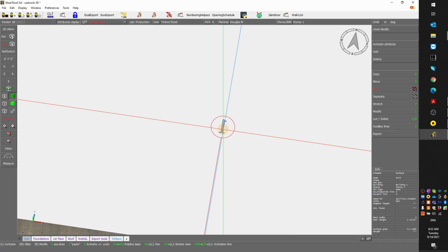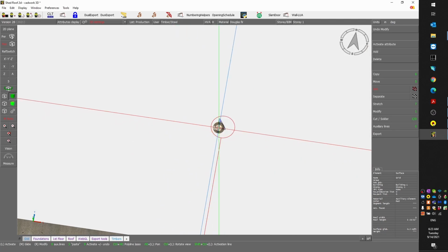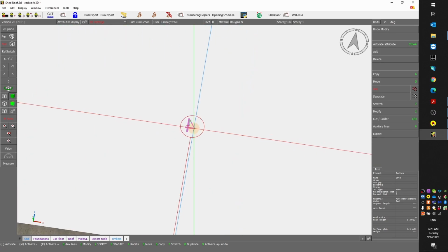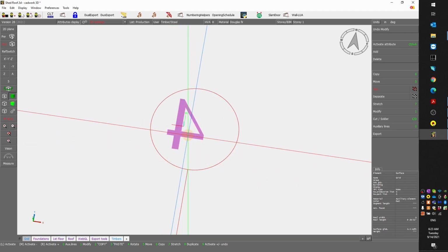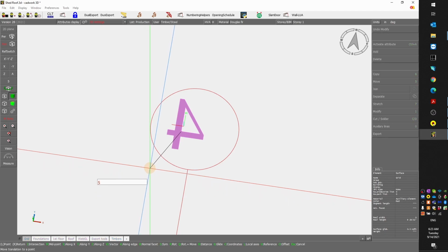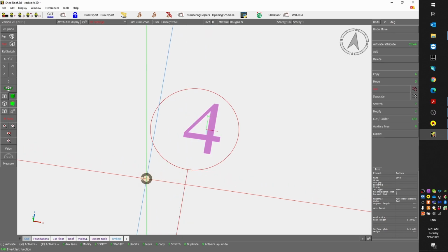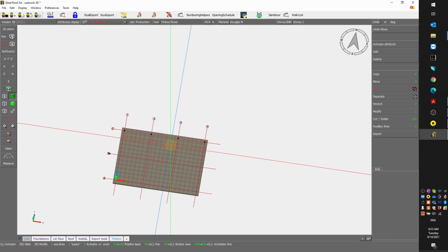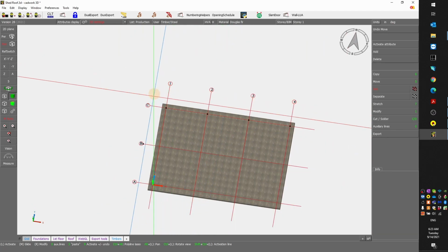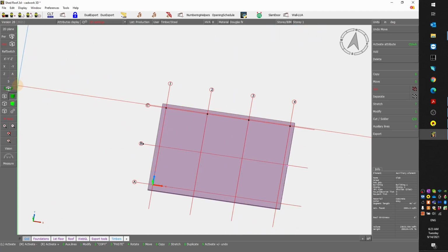And the last one here, because I made a horizontal copy, symmetry, it turned that on, like mirrored it. So what I can do, I can press 5 to fix it, S, X, and I can click here and it just reverted that letter. Okay, so now I'm all set with the grids and the slab. I can continue with my first column.